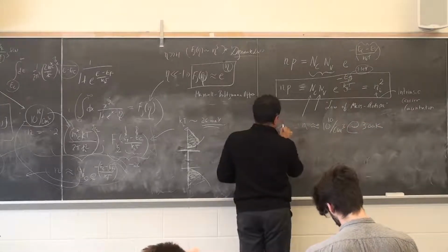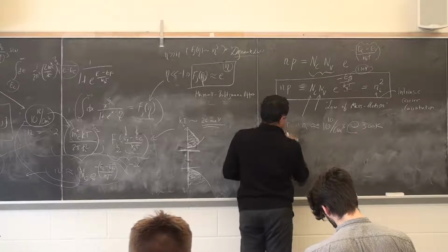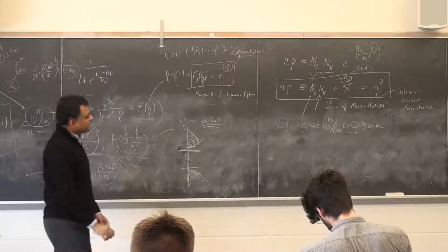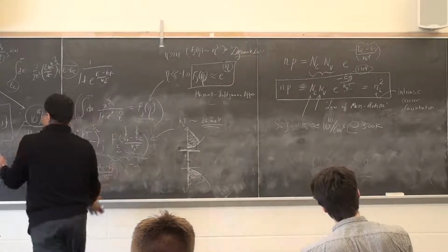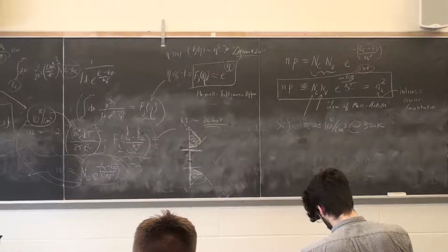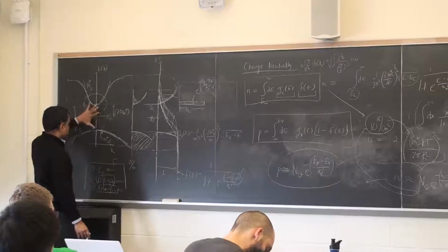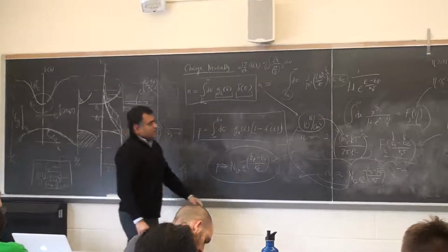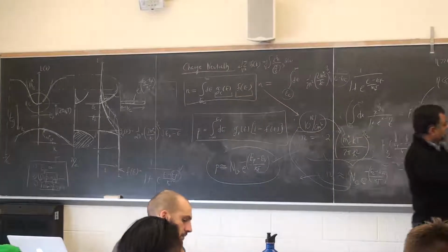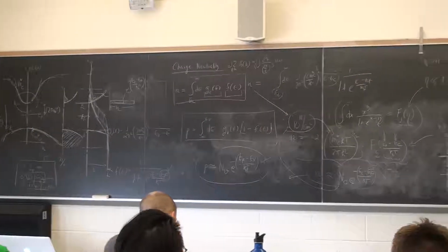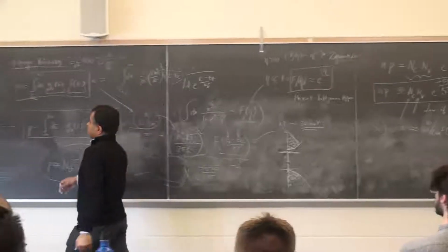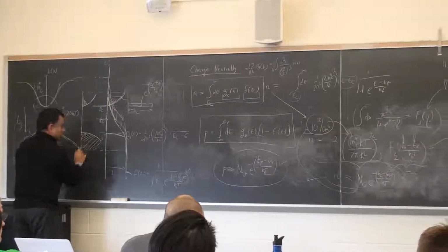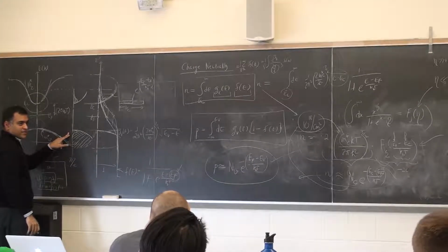Okay. So, this is, right? So of the order, that's how many carriers you have per centimeter cube. If you have a pure silicon sample with a gap of 1.1 electron volt and effective masses and all that detail at room temperature, that's what it means. And just to compare, how many free carriers do you have? Rather, this is the number of electrons you have in the conduction band and exactly equal to the number of holes you have in the valence band.